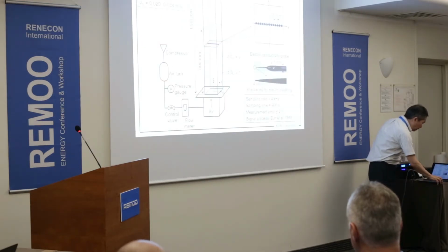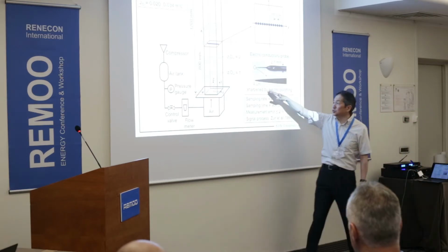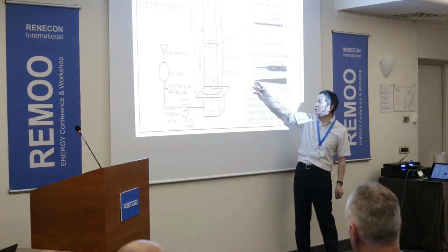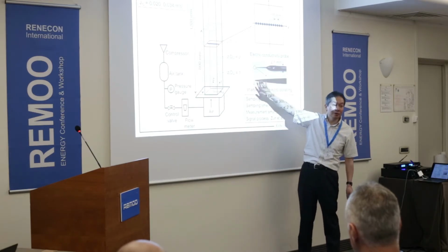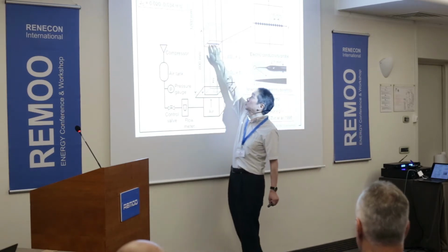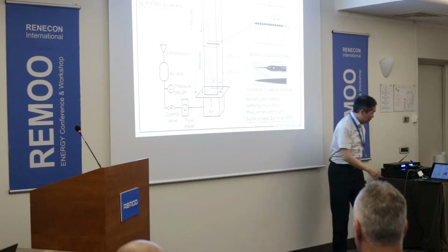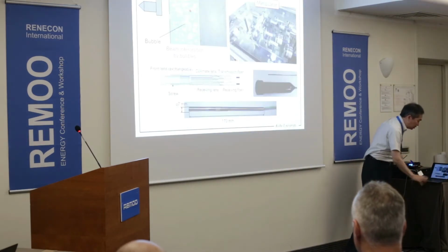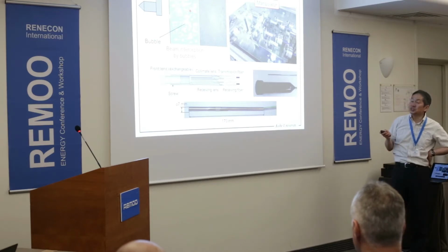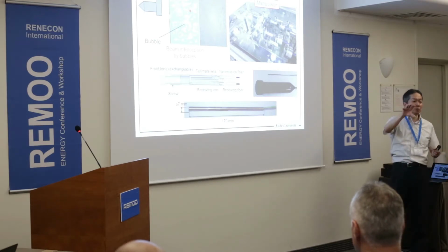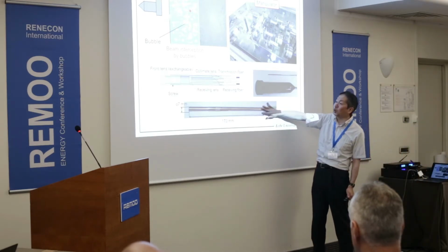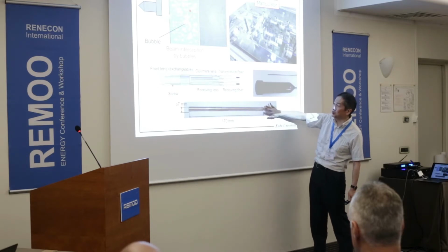So we did this experiment. We measured using the conductivity probe like you did. In our case, the tip diameter is 4 micron, a very tiny tip, and we measured the void distribution along this line. To measure the velocity, we cannot use a standard LDV system because bubbles block the laser light, so we developed our own laser Doppler velocimetry probe.